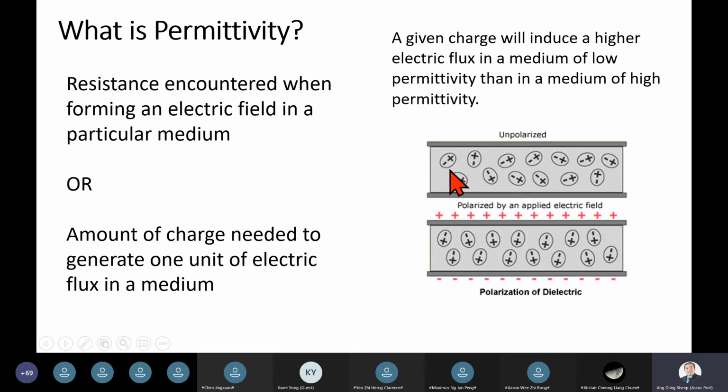For example, in a compound semiconductor such as gallium arsenide, gallium and arsenic have different electronegativity, so when you form a compound with two elements of different electronegativity, there will be non-equal sharing of charge, because one element tends to like electrons more than the other. As a result, the gallium arsenide molecule is actually polar. In other words, one part of the molecule is slightly positive with respect to the other.